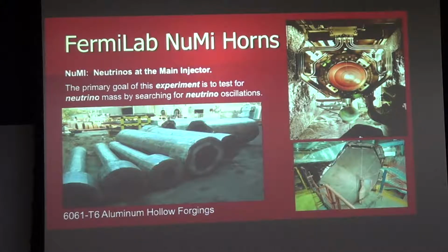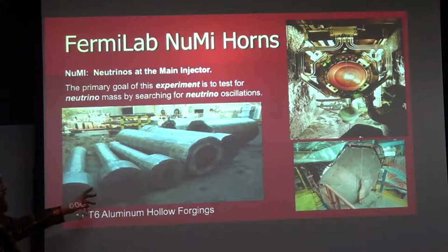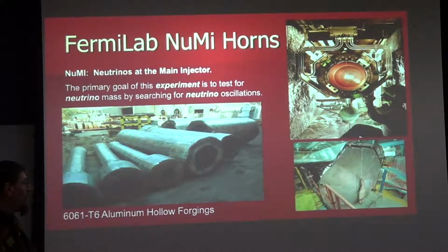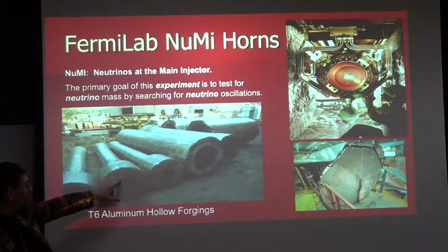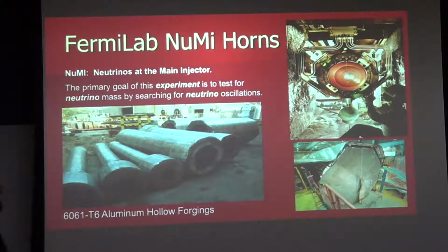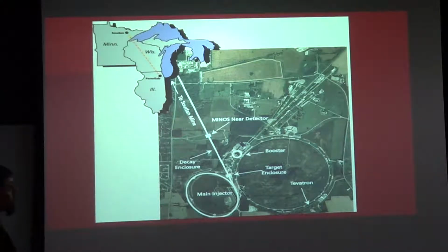This one, these are aluminum, again. You can see that one of the things, and we'll talk about this more later, but the forging process allows you to make things that are relatively close to the final shape. We call it near net shape, or sometimes semi-finished. So you can see we have a hole that goes all the way through. We've got multiple diameters all in one piece. That's one of the advantages of forging. We'll talk about that later in the lecture. That particular set of parts was used just south of us, where they have a large particle accelerator.